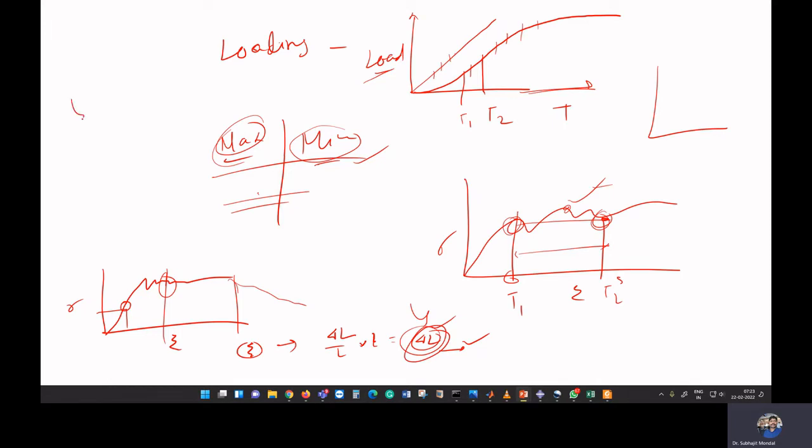In the step also you can control the increment. But the control you are doing there is indirectly controlling the loading. In this step you can give some time increment, you can modify something, but that will lead to your loading increment indirectly. So these are the things you have to keep in mind while doing nonlinear analysis.